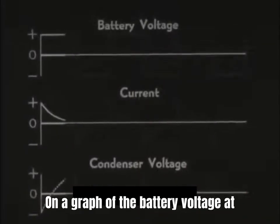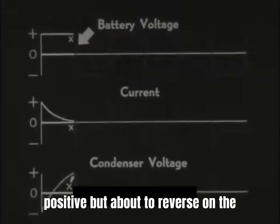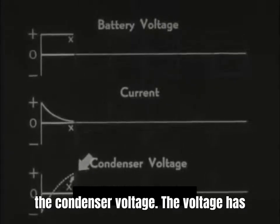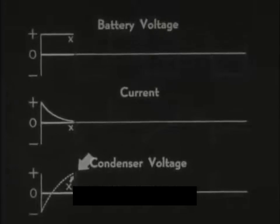On a graph of the battery voltage at a point marked X, a condition may be assumed when the voltage is still positive but about to reverse. On the current curve, the current has then reached practically 0. On the curve of the condenser voltage, the voltage has reached a value substantially equal to the battery EMF.